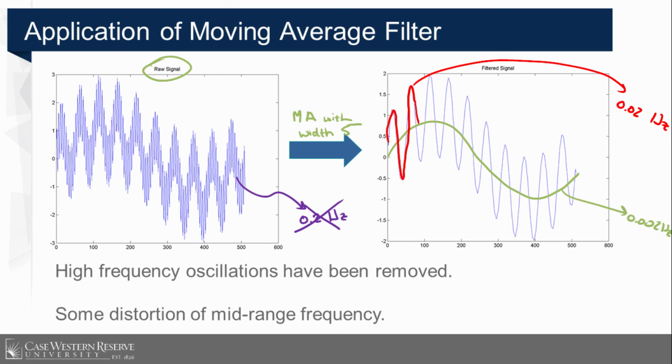All right, so here we've chosen to apply our filter in the time domain by performing a convolution. Well, we could do exactly the same thing by applying our filter in the frequency domain after performing a DFT on both our raw signal and our impulse response. So both would be equivalent, and I would encourage you to actually apply filters both in the time domain and in the frequency domain when we're looking at digital filters.